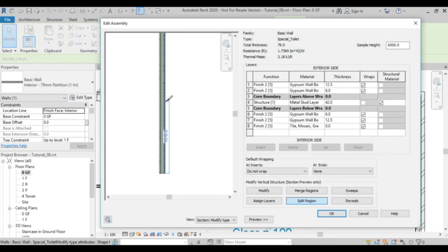A little bit down. Yeah, okay. Somehow very tricky. I need a value of 1000. That's the one. And I'll click. Once this turns to variable, it means you are successful, because this is what we want. Now you cannot simply assign. What you need to do now is click on modify. Don't make the mistake of pressing escape. Just simply click on modify.